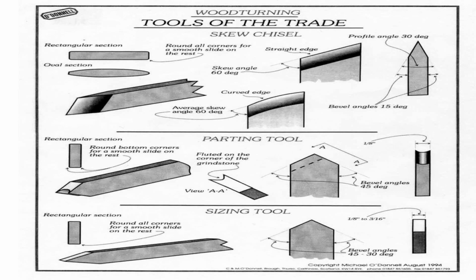Parting tools. There is an absolute variety of parting tools. My favorite parting tool isn't even up here. It's an old industrial hacksaw blade that's about this long and about that wide, and it's only about 35 or 40 thousandths thick, and it gives me the best parting tool I've ever had.